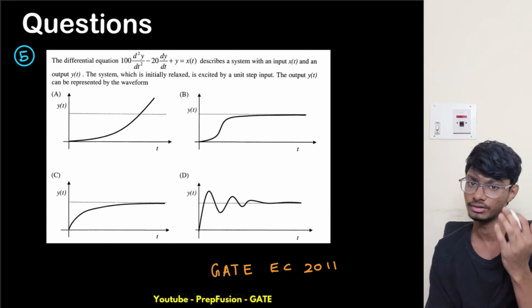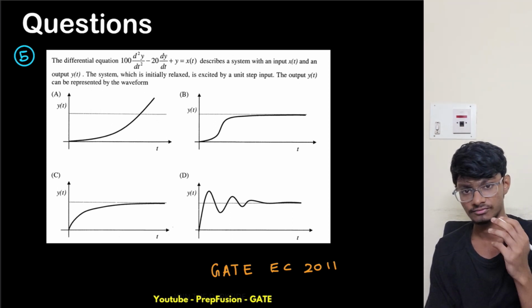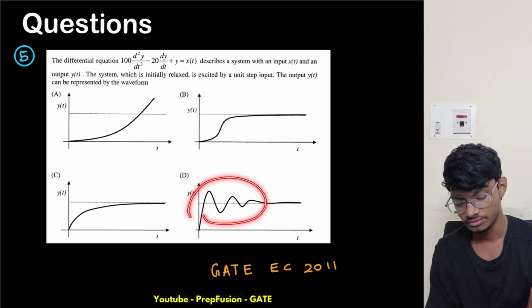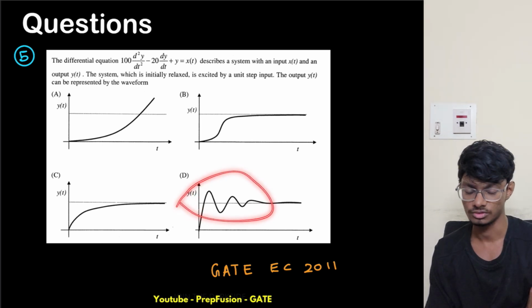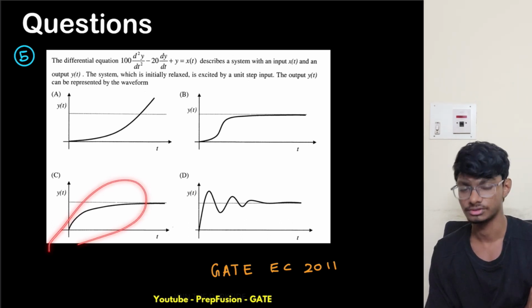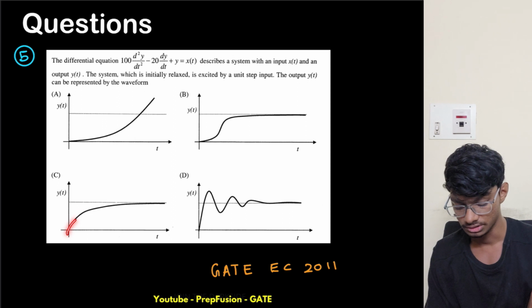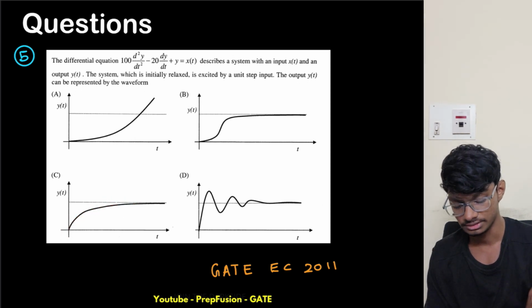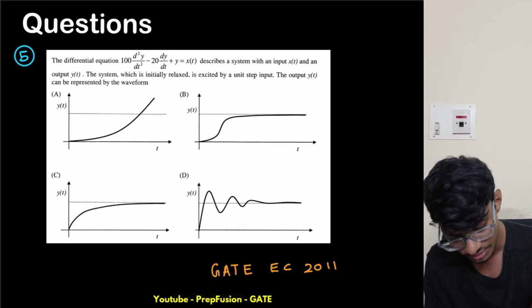Else if it had come out stable, then you would have to check the value of zeta. The value of zeta will be 0 to 1 for this one, because this is underdamped. It is oscillating, then reaching steady state. The value of zeta for this one will be exactly 1, because this is reaching steady state very fast.